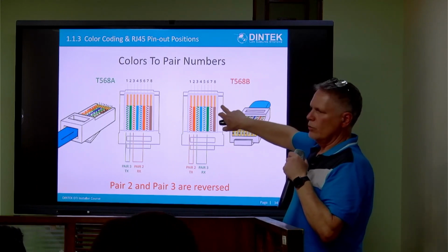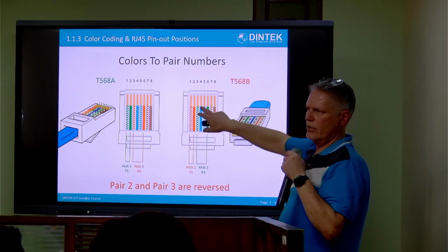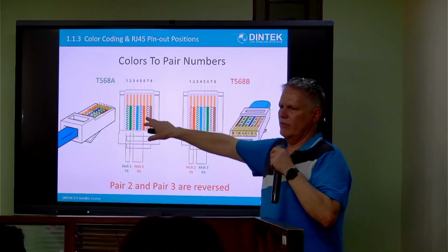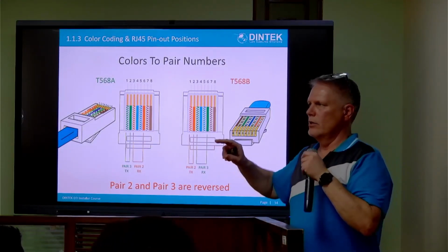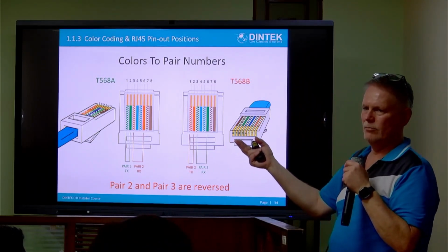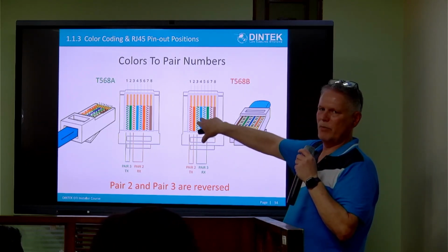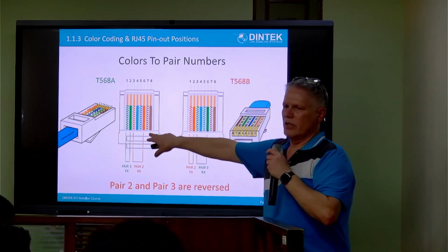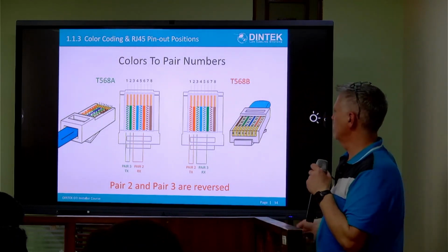This was our original specification. It was called T568. And then in 1995, when they revised the standards, they brought in T568A. So the EIA/TIA standards authority said, right, we're going to lead with the green pair instead. And you had different organisations saying, we don't want to change the specs. So they said, right, let's have 2. Predominant 568A, and we'll keep the old one and call it T568B.